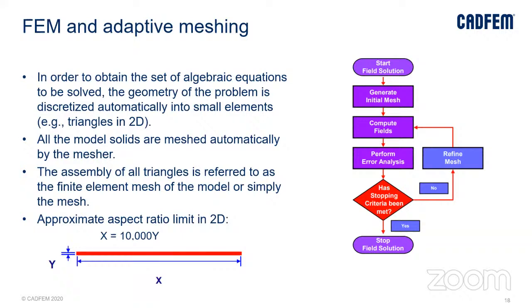That is the basic idea, and what these solvers offer is similar, because they offer two things: one is adaptive meshing technology and the other is manual mesh control. The auto adaptive mesh control helps the engineer automatically improve the mesh quality as per the field gradients wherever they are very high. So this automatically improves the accuracy levels generally.